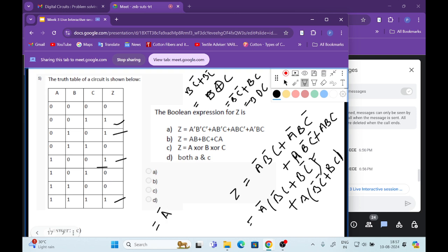Okay, so I am here writing A bar, that means B XOR C plus A B XNOR C, right? And in the previous slide we also see that XNOR is just the opposite, or inverter, of XOR gate. So this expression B XNOR C we can also write in this form, B XOR C bar, right?